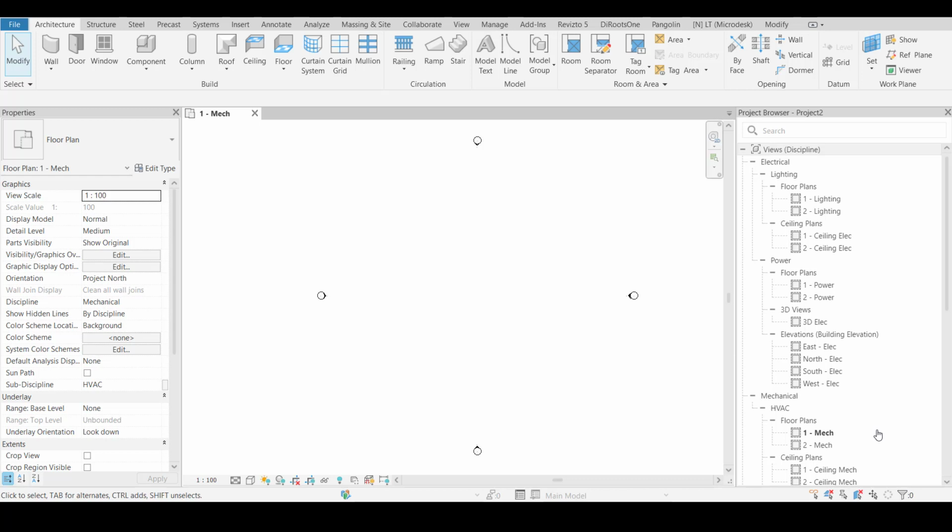Okay, now the next process is making the shop drawing or LOD 400, where the contractor comes and prepares the installation drawings. That part comes later. After the design part, the construction part comes, and at that stage the person who is appointed, the main contractor or contractor, starts working on their drawing with reference to the IFC drawing.